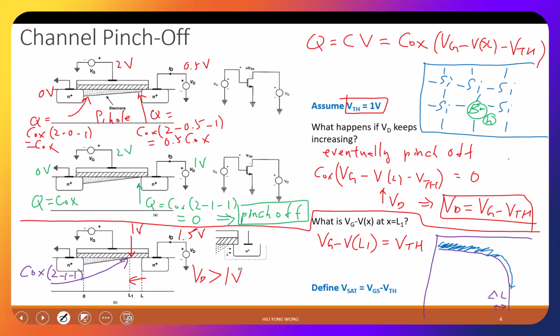So you can say, okay, at the waterfall, you barely have any water, barely have any electron. But because of the continuity, you do run very fast. Whatever comes in, runs very fast. Here you have slower electrons, but here you have faster electrons. So overall, you do have a current going through. You can think in this way. Yeah, so again, very good question. Pinch off is just a simplified model, but it's a good way to think about that.